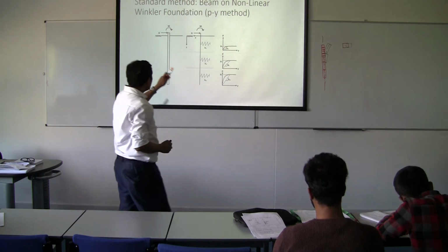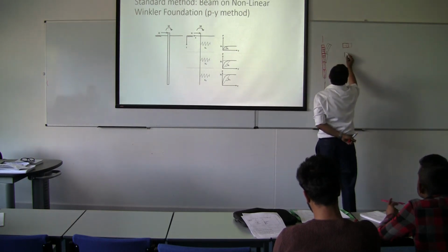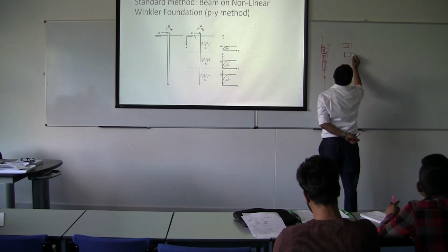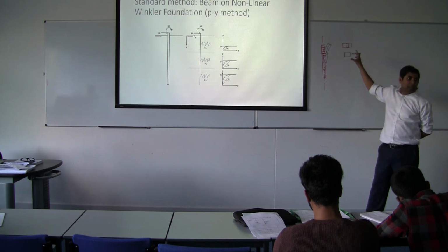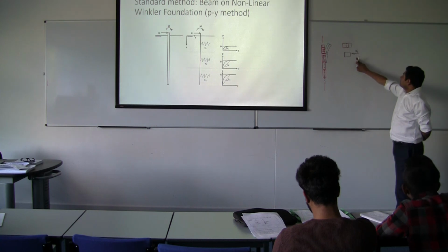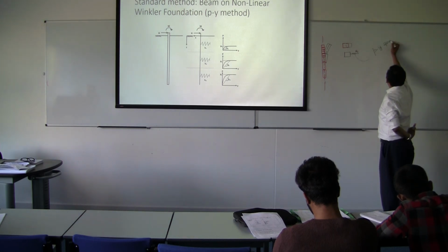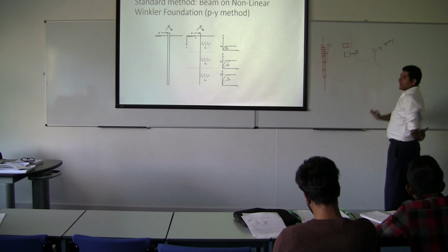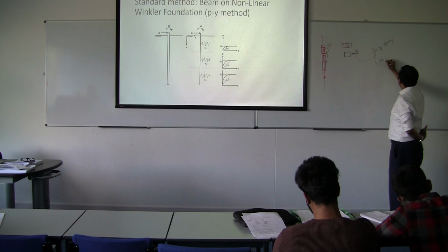Yeah. So what does this spring represent? So the model now becomes, and that is K1, isn't it? K or P-Y spring. Now, what it is doing, these springs are known as P-Y springs, and what they are doing, they are trying to capture the pile-soil behavior.